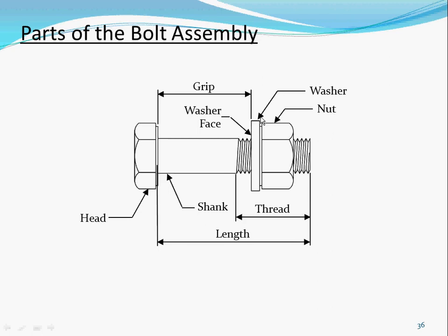The washers are typically required when you're pre-tensioning any kind of connection. Their use is because of the area of the head, you might be digging into the steel a little bit, so they're trying to spread out the load. That's why the washers are there, so you don't dig into the soft material over a smaller area. That's why there's a chapter in the RCSC: when do you use washers, and what type of washers do you use?